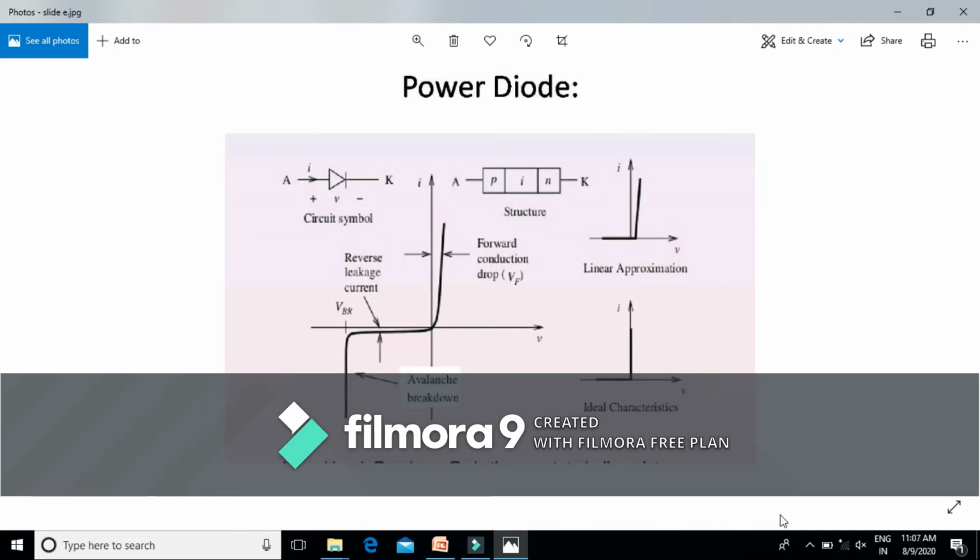So it should be kept in mind that a junction with a lightly doped layer on one side requires a large breakdown voltage, and a junction with highly doped layers on both sides requires a low breakdown voltage.